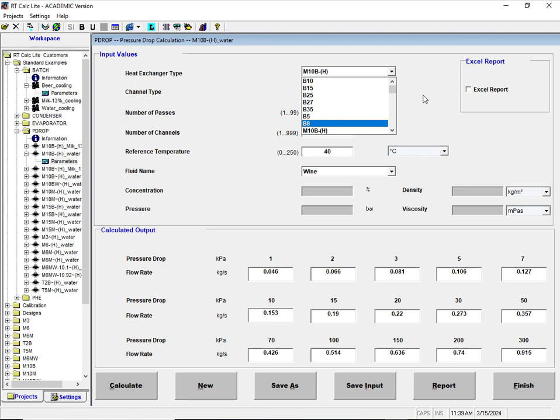And the standard, what they call counterflow correction factor, for when you're going counterflow correction is 1. When you're going for parallel flow, it's a half. So you're actually reducing the effective heat transfer by half just by routing it incorrectly. You can be very careful on your ins and outs on a plate exchanger or any exchanger. You have to be very careful. So the first part here literally is brazed plates, and then after that we move typically into the gasketed plates.